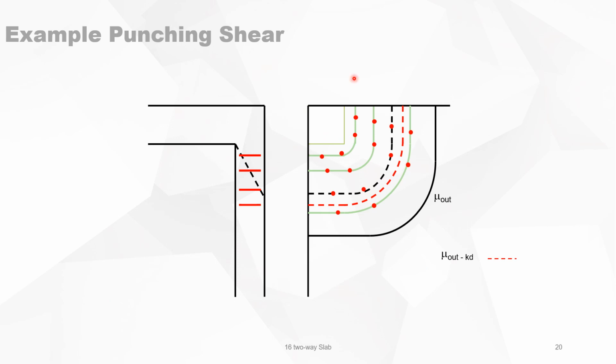Then we make a little drawing, and you will see the first, second, third, and fourth perimeter, and each perimeter has 4 diameter 8 bars evenly spread out over the perimeter. And if you make a cross section to it on the side, then it will look more or less like that. So this is how we have determined the needed shear reinforcement for a corner column.